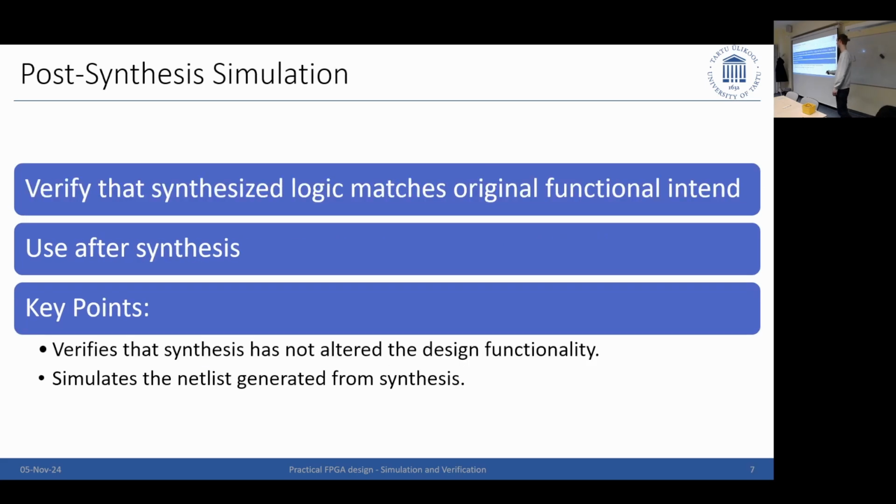Post-synthesis is a step in between, which aims to check if your synthesis tool translates your code correctly into logic elements, so that the synthesized logic matches the functional intended logic. This will not give me more precise timing delays, but it makes sure that my things work correctly.